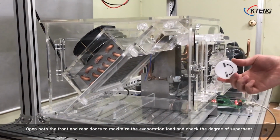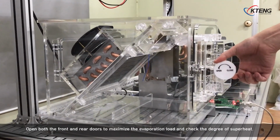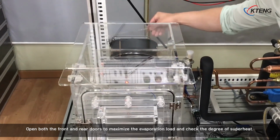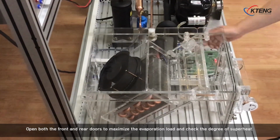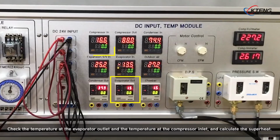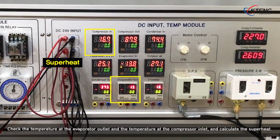Open both the front and rear doors to maximize the evaporation load and check the degree of superheat. Check the temperature at the evaporator outlet and the temperature at the compressor inlet, and calculate the superheat.